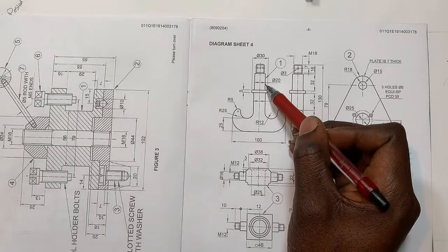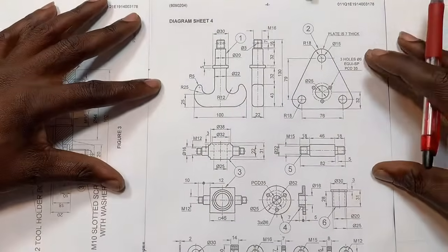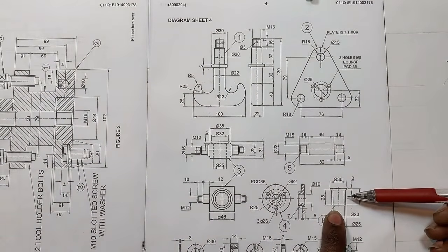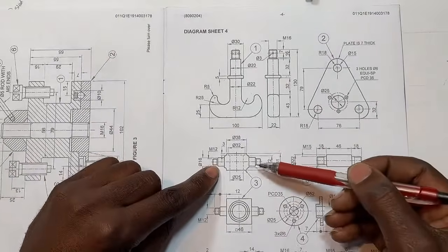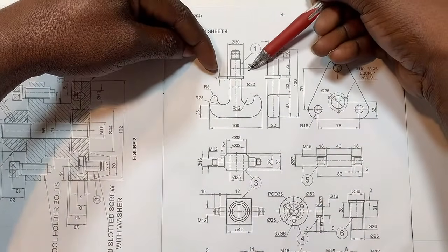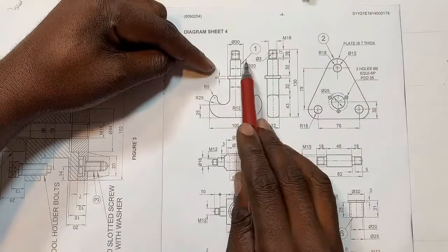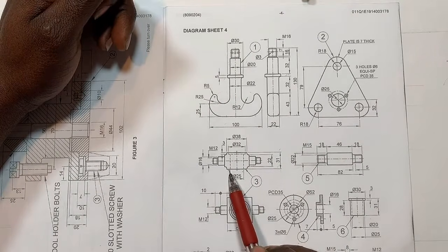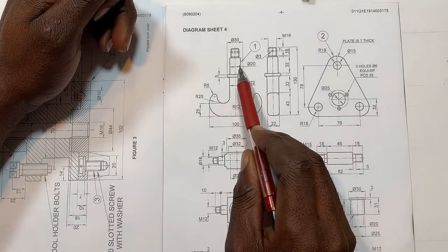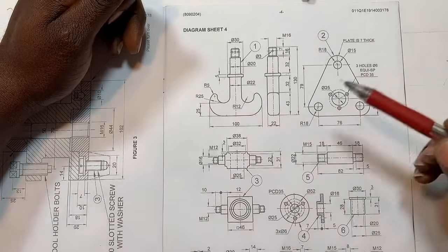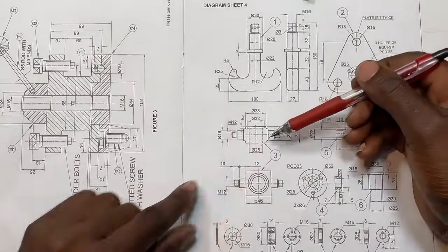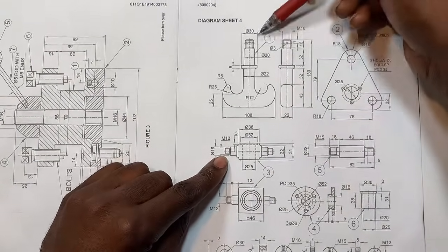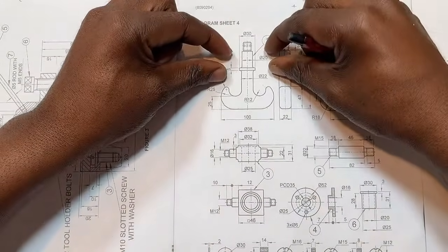This is quite interesting, which means before you put your item 3, you take item 3 and fit it in there. When you fit it in there, there will be a play there. Why? Because this is diameter 25, and this one is diameter 25, whereas there is diameter 20. Let me explain this. When you take item 3, this is the front view of item 3, this is the top view of item 3. When you take item 3, you fit it into item 1, take it like this, you fit it in there. There will be a play, isn't it?